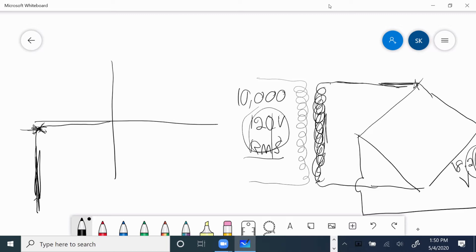Now, if the junction of the Zener diode is capable of carrying or tolerating this current, then how much this voltage will increase to is really not the point. And since it is at a very short period, it is not going to ruin it. It's not going to harm it.